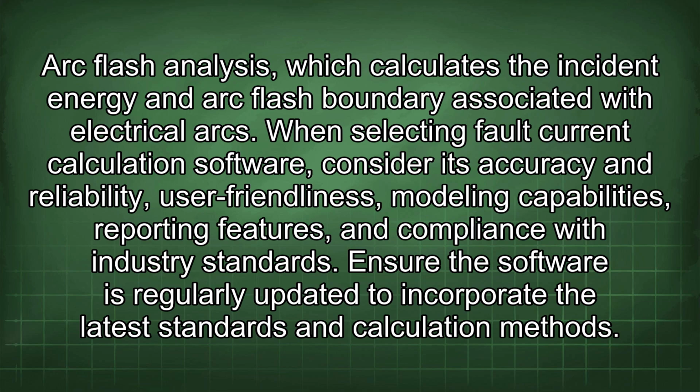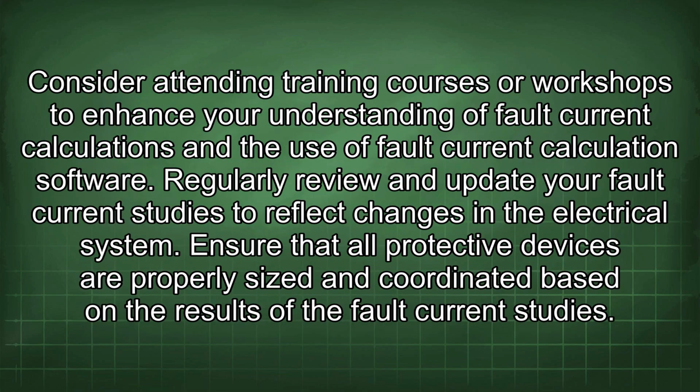When selecting fault current calculation software, consider its accuracy and reliability, user-friendliness, modeling capabilities, reporting features, and compliance with industry standards. Ensure the software is regularly updated to incorporate the latest standards and calculation methods. Consider attending training courses or workshops to enhance your understanding of fault current calculations and the use of fault current calculation software. Regularly review and update your fault current studies to reflect changes in the electrical system. Ensure that all protective devices are properly sized and coordinated based on the results of the fault current studies.